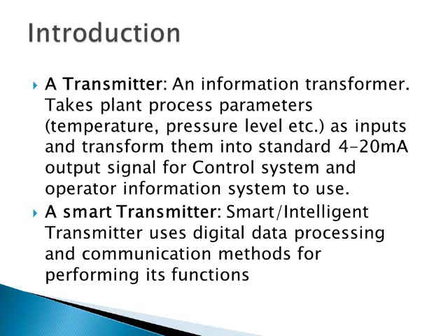I'll just quickly go over what a transmitter is, because it is basically a transducer. It reads the input signals, temperature or pressure, as I already said, and then converts them to a 4 to 20 milliamp signal. Now, when you add smartness to it, we can change its configuration online. We have the communication facility, and we can save data online also. These are good features for the conventional industry, and also for the nuclear industry, but not essential. But since it is there, we have to look into it.